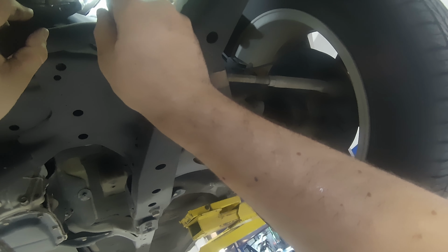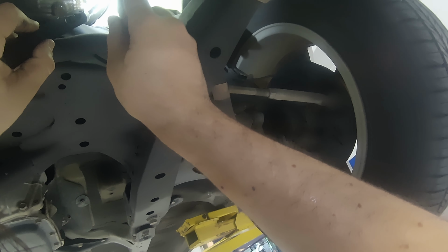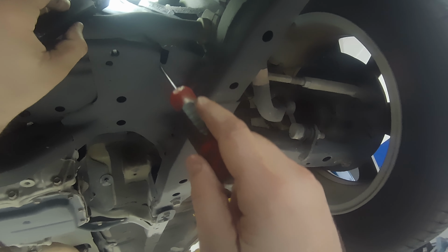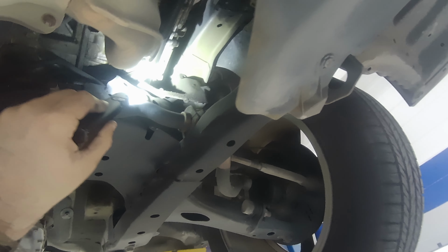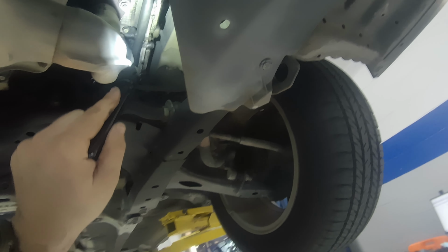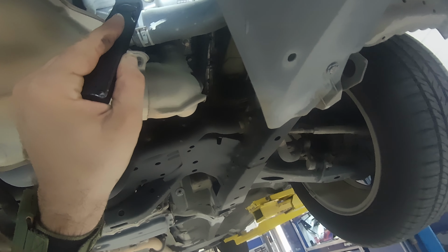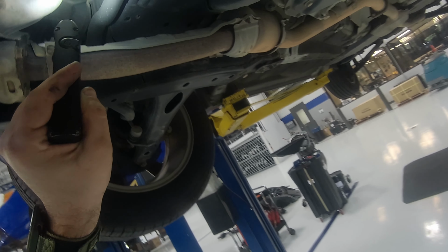So you see this nice clean spot right here. This is the leaky spot. And over here, this is just all the drafted air. So these valve covers at least need to be replaced.